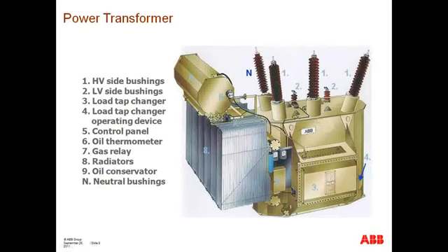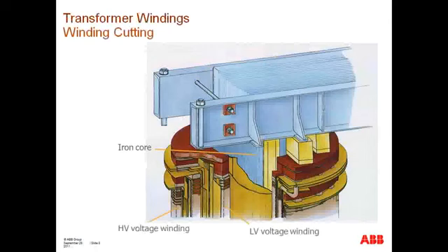If that thermal rise continues to go up and continues to go up, then it's not only pressure, but damage that can occur to some of the elements that form the transformer. So an important point is, transformers have a certain thermal operating rating that's associated with the amount of power and the ambient temperature, and those thermal ratings cannot be exceeded. And we'll have some discussions about that later on in our presentation.